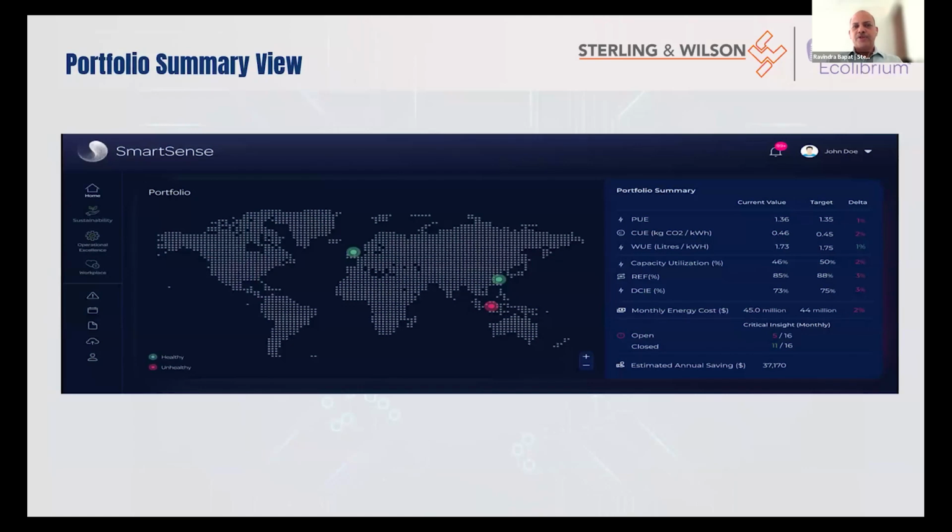Now, from the monitoring perspective, let's say I have data centers across, say, Singapore, one in China, one in Europe. Everything I can monitor in one dashboard, looking at what is happening in which facility, whether my PUE is fine. PUE stands for power usage effectiveness, which is a kind of energy factor for a data center, which tells how efficiently it is running, or whether there are more losses in the data center. And there is scope to improve that. That means obviously it is directly connected to your energy bill. So it's an important factor for any operator or any data center player for that matter.